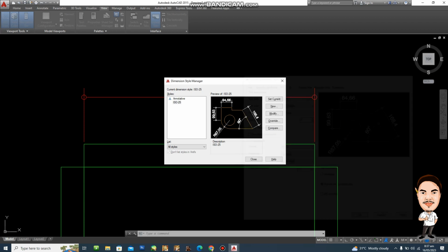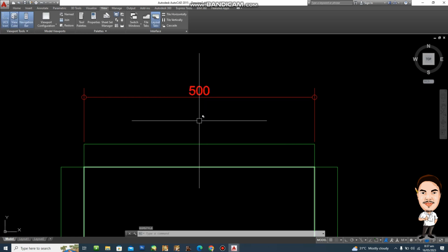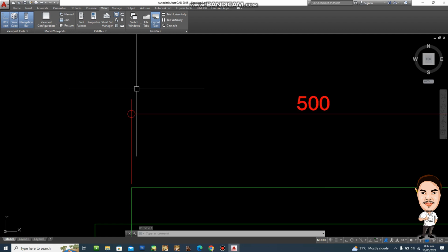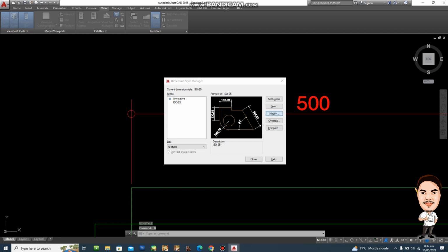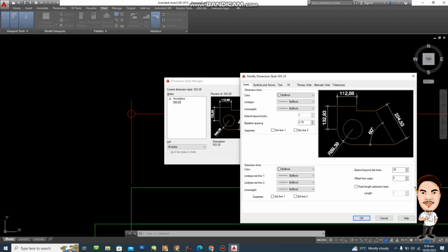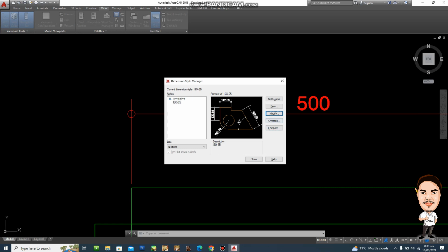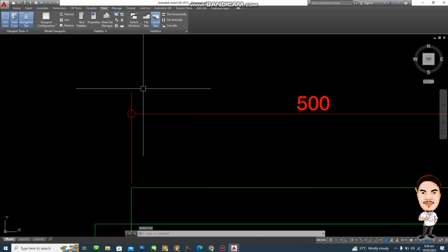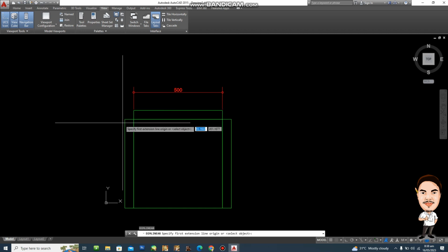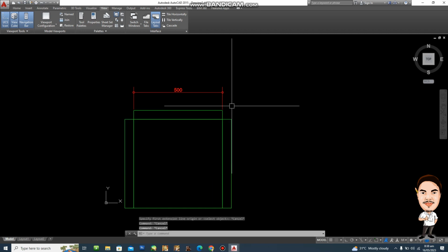And then offset from the dimension line, we'll change it to 5. Let us check the changes. Okay, so this is better, but there's a need for us to extend more the terminating line or the dimension line here. So let us extend it a little bit. We'll go with the lines and then extend beyond the dimension line. Let's change it to 30. Okay. Set current. So as you can see here, we have a better dimensioning style here. So this will be the time for us to dimension other areas.